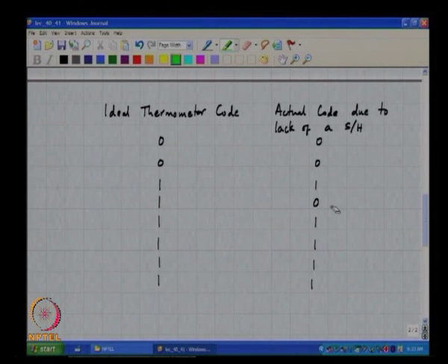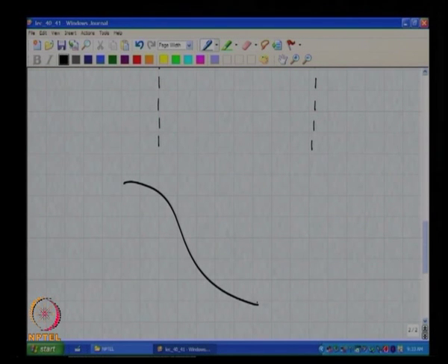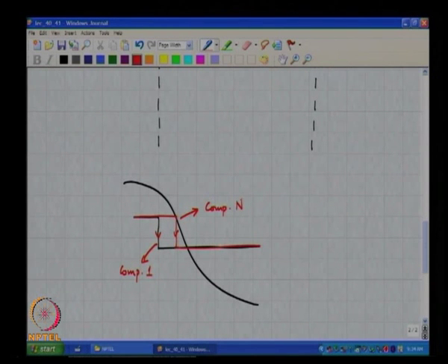One, there is no sample and hold. If there was a sample and hold, what do you think will happen? Okay, so let us say this is the input and there is clock skew. So, for instance, this would be the sampling edge at comparator 1, and because of clock skew effects this would perhaps be the sampling edge of comparator n. So, the first comparator is actually digitizing this point, the last comparator is making a decision on that point, and the comparators in the middle are comparing something in the middle to their references.